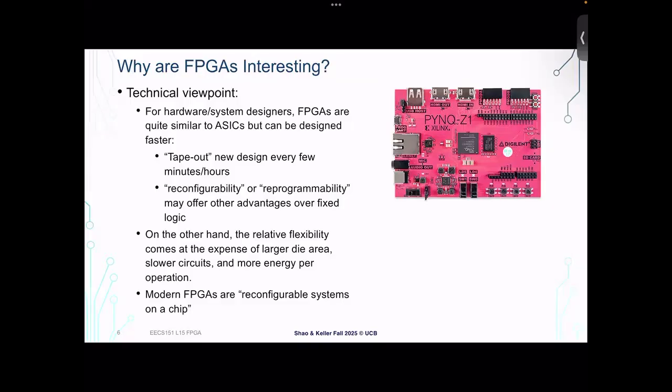The disadvantage of FPGAs is that in order to get that programmability, you're worse on the magic metrics, right? PPA, power performance area. So FPGAs are not as efficient as ASICs for any given task that they've been programmed for. So it's a trade-off. And then modern FPGAs have taken that basic concept and added lots more bells and whistles. And we'll talk a bit about all the extra goodies that you can find on a modern FPGA beyond just this kind of sea of programmable blocks.